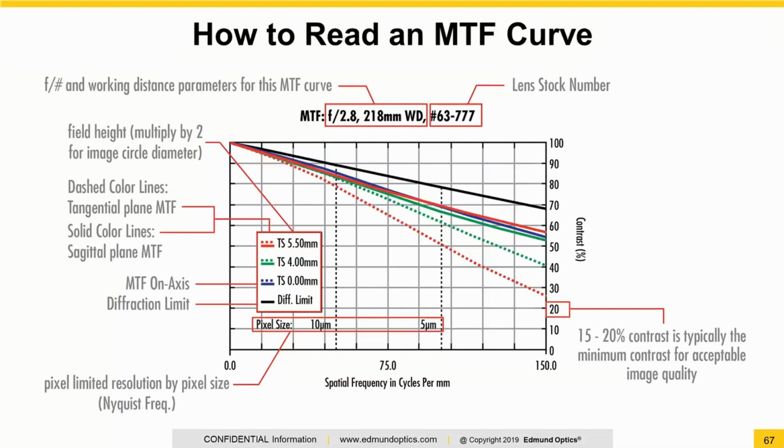But if we go out to the corner of the image plane, we have 5.5 millimeters. In this particular case, 5.5 is equal to the half diagonal of a 2/3 inch image sensor. The reason why we give the half diagonals, because optics are rotationally symmetric, is that we like to cut numbers in half quite a bit. We could show negative 5.5 millimeters, but it would overlay directly on top of the 5.5. So to reduce redundancy, we just cut that out, and we're showing the center as blue, the bottom middle as green, and the corner as red.